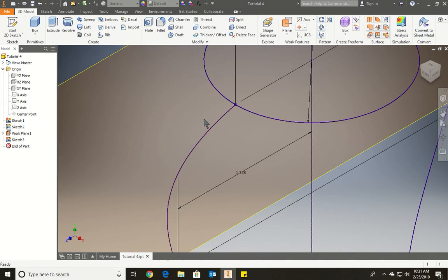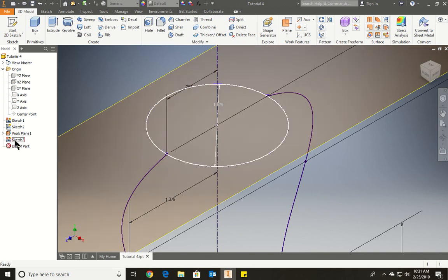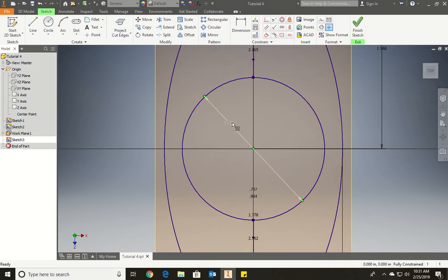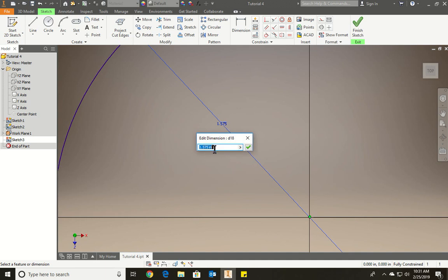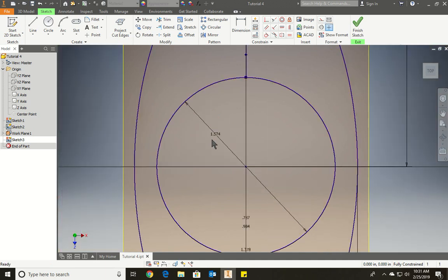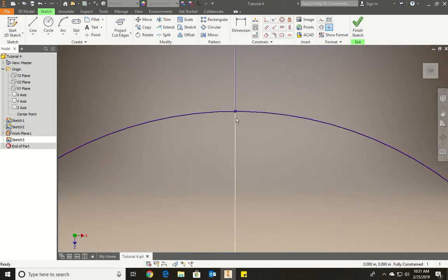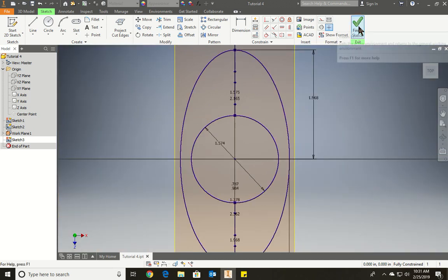Since it's a little error, we're going to change that number. We're going to go to Sketch, edit the sketch, and change this by one number. You're saying 7.4, which makes it a little bit smaller, which I guess makes it touch the actual lines. Press Finish Sketch. Oh, what we could have done is just do a circle from here to touch of that. That would have been a lot easier.